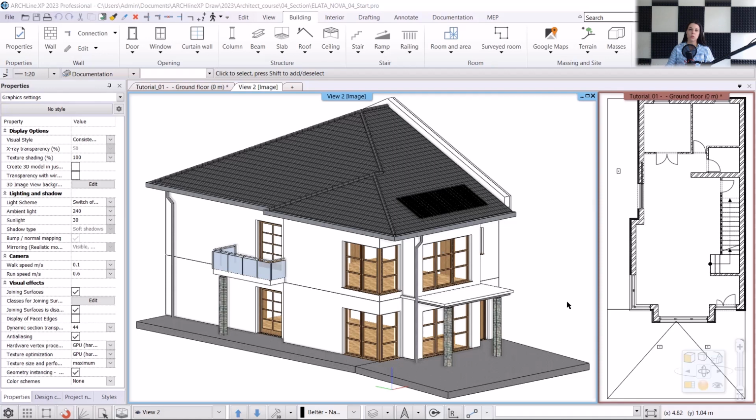If a visible 3D view is associated with an existing section, we can update it using the View Create Update command. Sections and elevations can be created in two ways, as raster image or vector drawing. Raster images are more efficient and versatile, while vector drawings offer higher precision. Both sections and elevations can include dimensions, annotations, level lines, tags, grid lines, and various other elements.